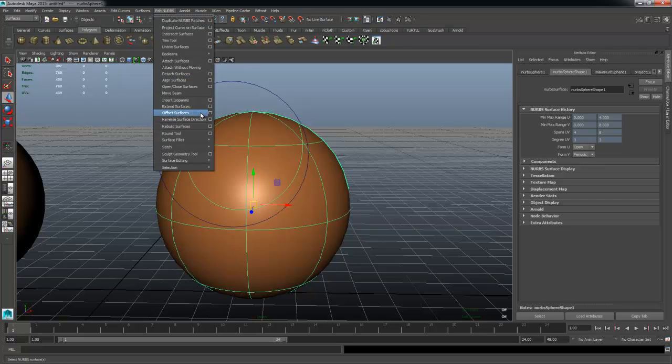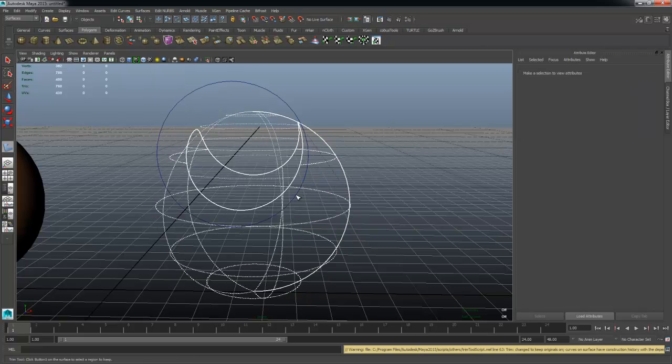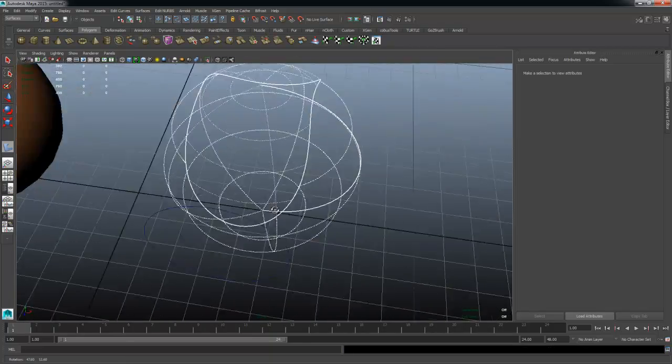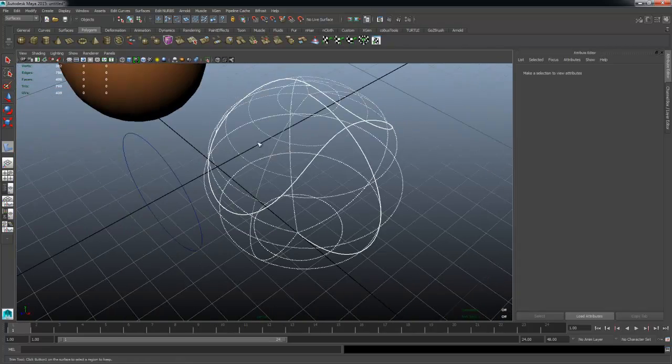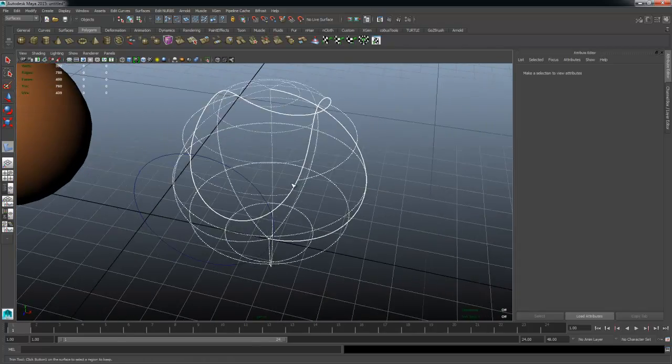We can either decide to cut based on that projected curve, or we can say maybe we want to trim the edge so that we take away everything outside of the shape, or maybe everything that's inside the shape. So if we go to the trim tool, Maya is asking me, what do I want to have left behind, or what do you want to take away?